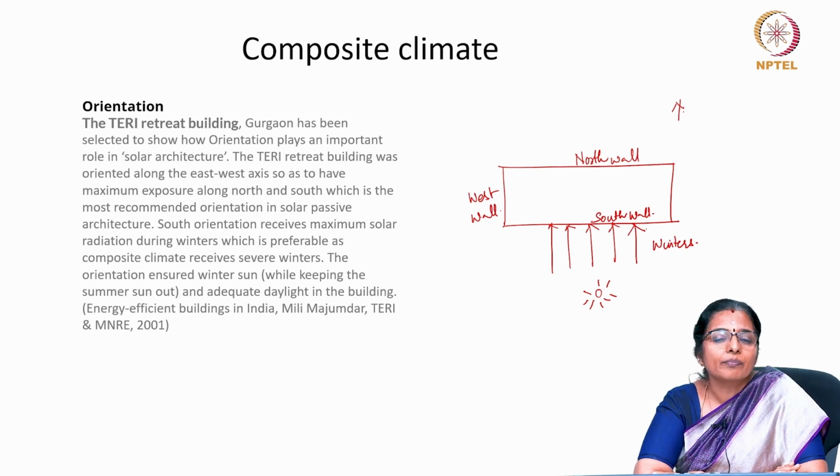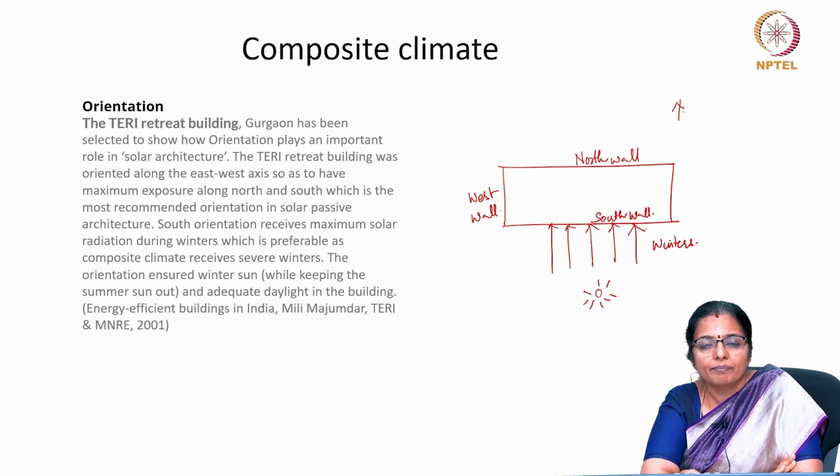Hygienic reasons, meaning algal growth and fungal growth, have to be curbed. Otherwise, mold growth can become a big problem. Shelter should be provided from the winter winds, and the buildings are preferably rather compact. However, because of the conflicting climate conditions, you have two kinds of climate conditions, several solutions are possible depending upon local topographical conditions and functional requirements.